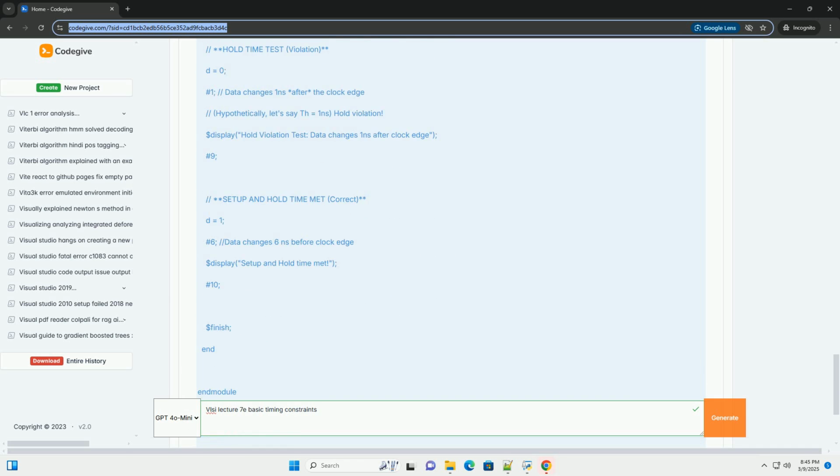Use static timing analysis, STA, tools and SDF files for accurate timing verification. Be aware of clock domain crossing, CDC, issues and use proper synchronization techniques. This detailed tutorial should give you a solid foundation in VLSI timing constraints.